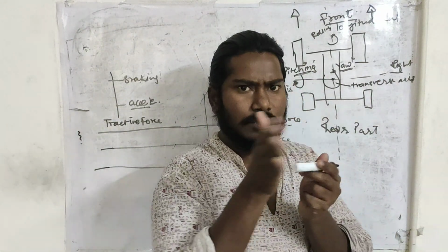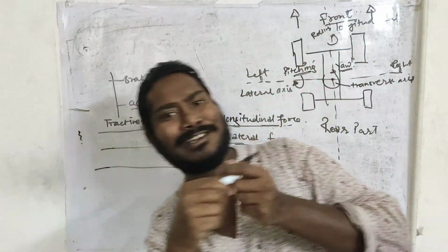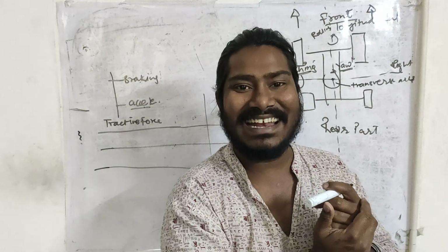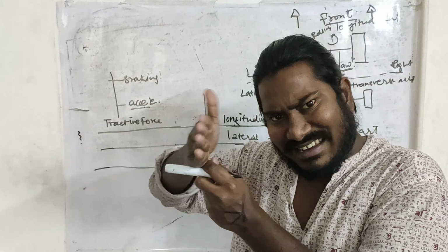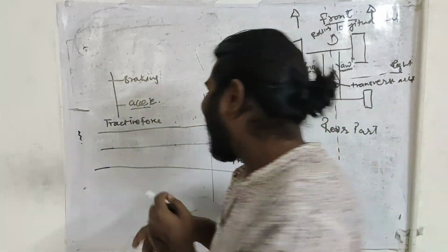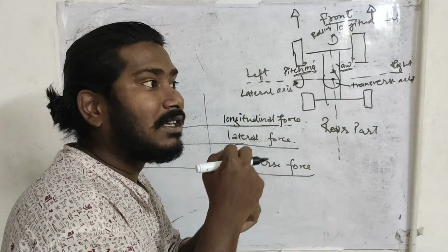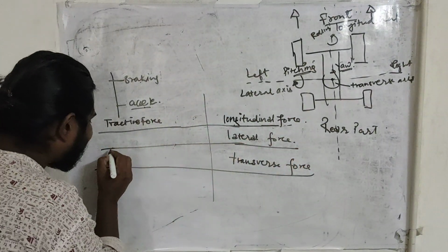Okay. Now lateral force. When I take a corner, this inertial force pushes me in the opposite direction, or the centripetal forces that are acting, right? When the tire is sticking, the slipping forces that are happening, the inherent property of the tire, the change in the shape of the tire causes this slipping force, right?